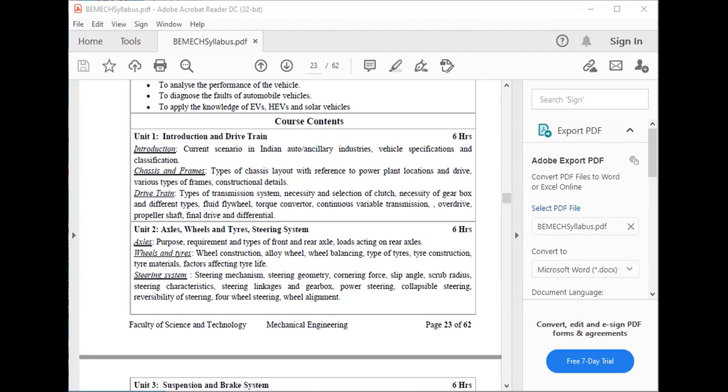Modern clutches typically use a compound organic resin with copper wire facing, or a ceramic material, which is used here. The coefficient of friction is 0.35 for organic and 0.25 for ceramic material. Ceramic materials are typically used in heavy applications such as trucks carrying large loads or racing.